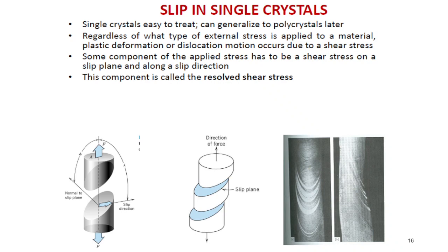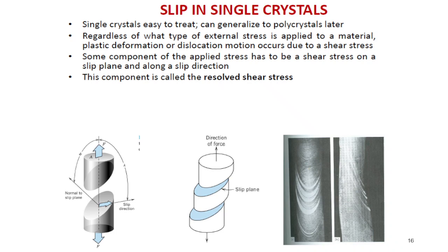Compressive loading. Usually, no matter what the loading is, shear stress only will be acting, be it compressive or tensile. So I believe it will still convert from HCP to FCC only. I don't think it will go the other way around. Anyhow, I'll verify and I'll let you know that.